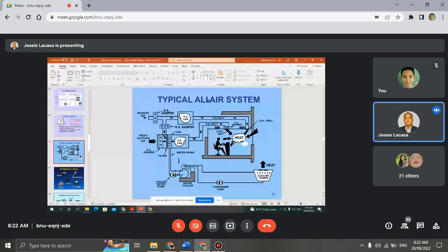So the first step in designing an air conditioning system is to calculate the cooling load, the cooling load calculation or heat load calculation, for the room. Not only for this room but for all the rooms it supplies, if our design is centralized. Okay? So, an example.